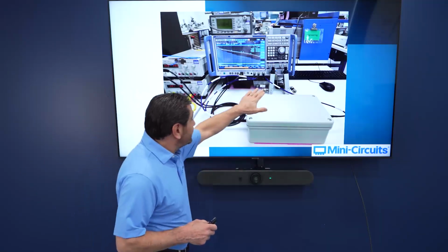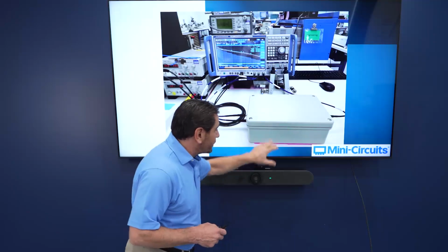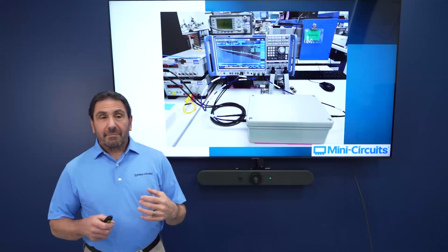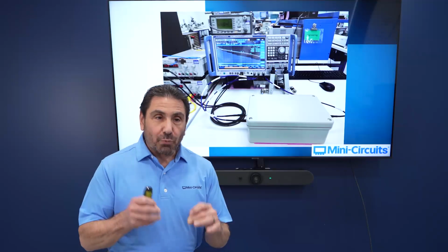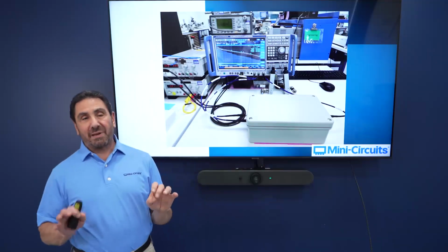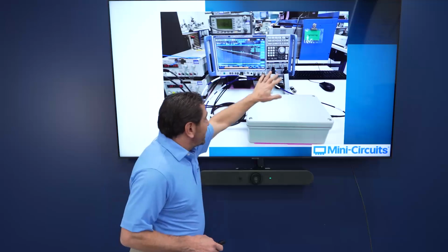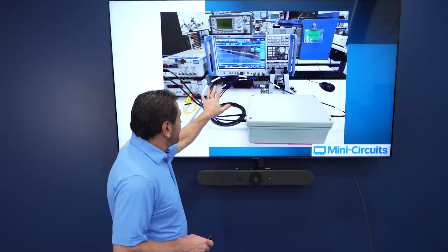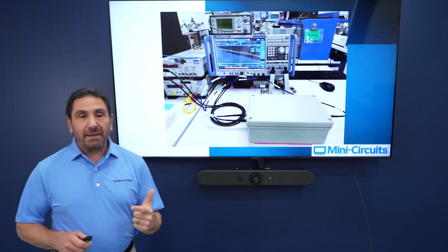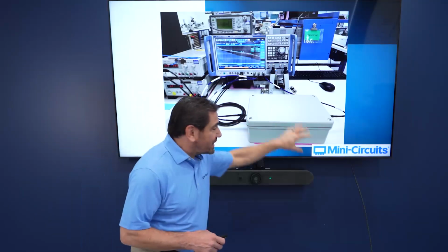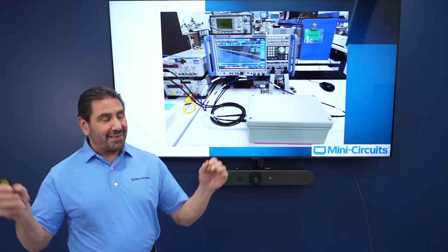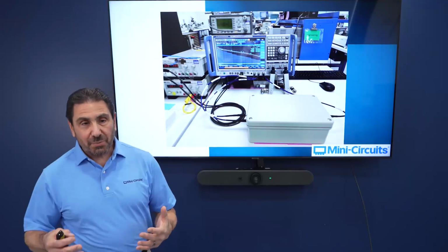Not only that, but you'll notice even the test equipment itself and this EMI enclosure are mounted on vibration absorbing material. This is our EMI box that the DUT resides within. It's very important that we keep any spurious, any type of electromagnetic interference out of the DUT while we're making these measurements. If you look at the phase noise analyzer itself, you'll notice there are three coaxial cables coming out of the analyzer. Those are DC voltages, very clean, provided by the test set, and we route them into our EMI enclosure and therefore to the DUT through coaxial, well-shielded cable. Very important. Anything on that DC, spurious, will perturb the measurement, and we don't want that.